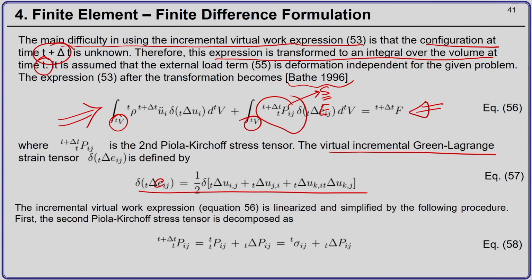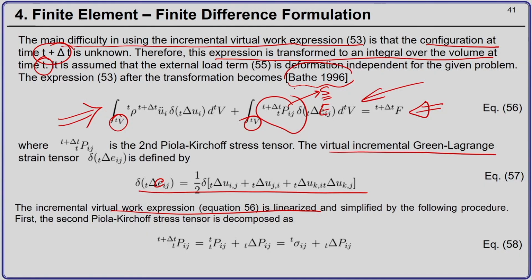Now, the incremental virtual work expression is a nonlinear expression. In our previous discussion, we first did the discretization and then the linearization, but here we follow Bathe, and as I mentioned in those lectures also, there is another way: you can do linearization first and discretization later, which is what Bathe follows. So in this current formulation we use linearization first. For linearization we use the following procedure.